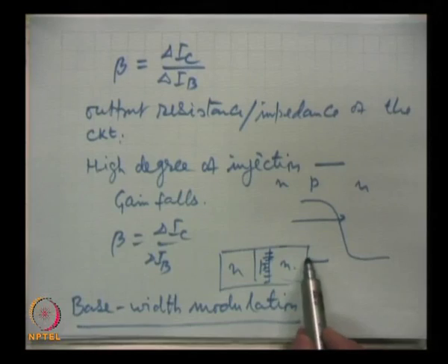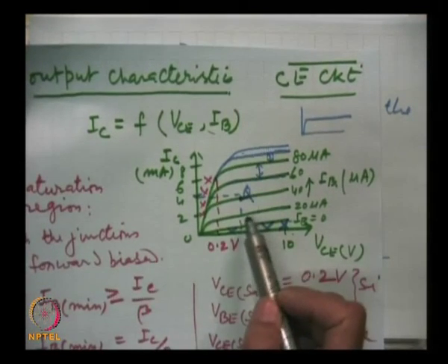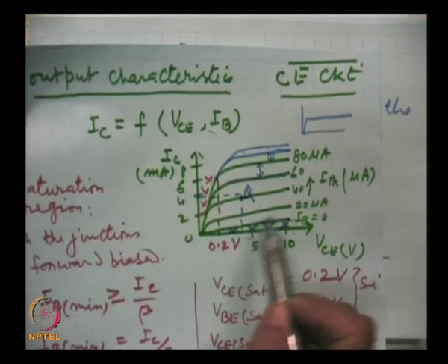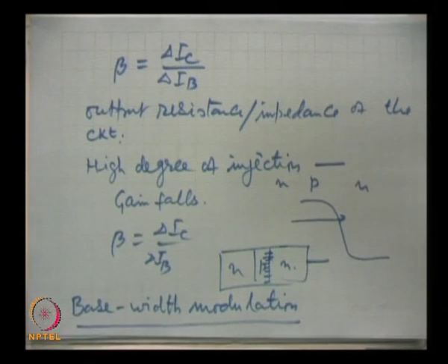With the rise of the reverse bias, the base width falls. So, a lesser number of charge carriers will recombine and the current will slightly rise. So, that explains these characteristics. We can get the current gain, and we can get the output impedance from the slope itself, and these are very useful characteristics. So, that covers the input and output characteristics of the transistor.